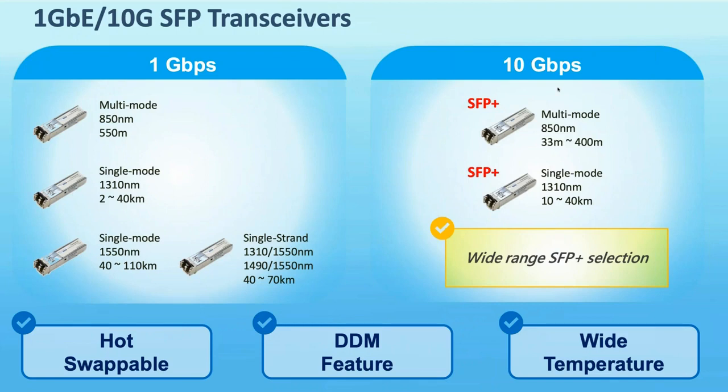For those of you unaware of the technology here, normally with fiber optics, you need 2 strands of fiber, one to transmit, one to receive. Single strand optics actually eliminates the need for a second strand, so we can use a simplex connection, 1 strand to connect 2 devices. So we can reduce cabling costs or double the capacity of a previously installed fiber system.